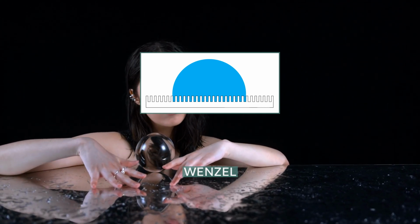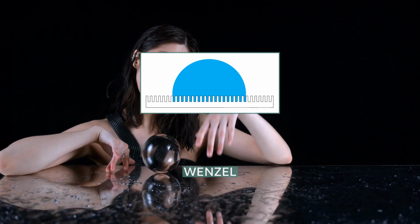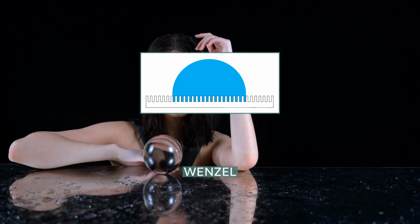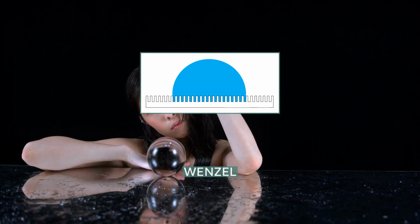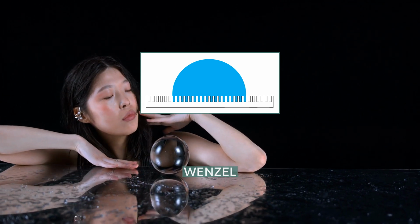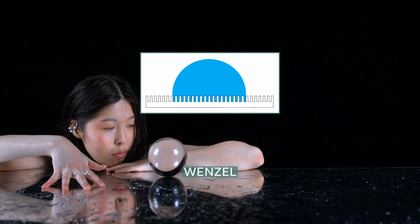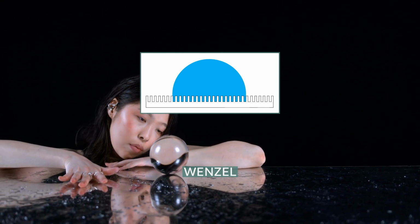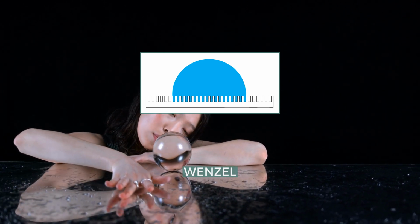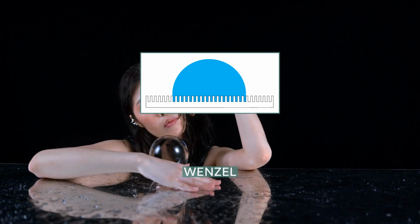The roughness ratio, r, is a measure of how surface roughness affects a homogeneous surface. The roughness ratio is defined as the ratio of true area of the solid surface to the apparent area. Theta is the Young contact angle as defined for an ideal surface. Although Wenzel's equation demonstrates the contact angle of a rough surface is different from the intrinsic contact angle, it does not describe contact angle hysteresis.